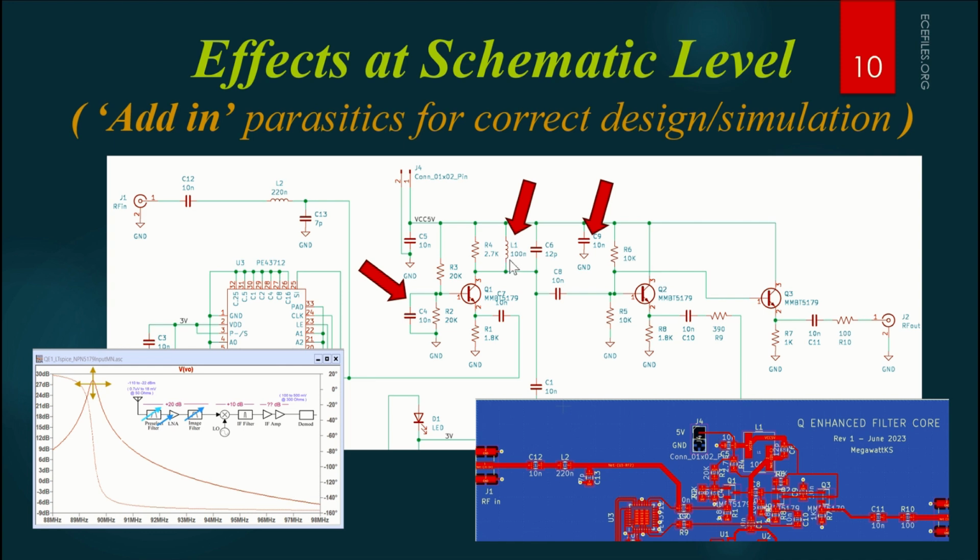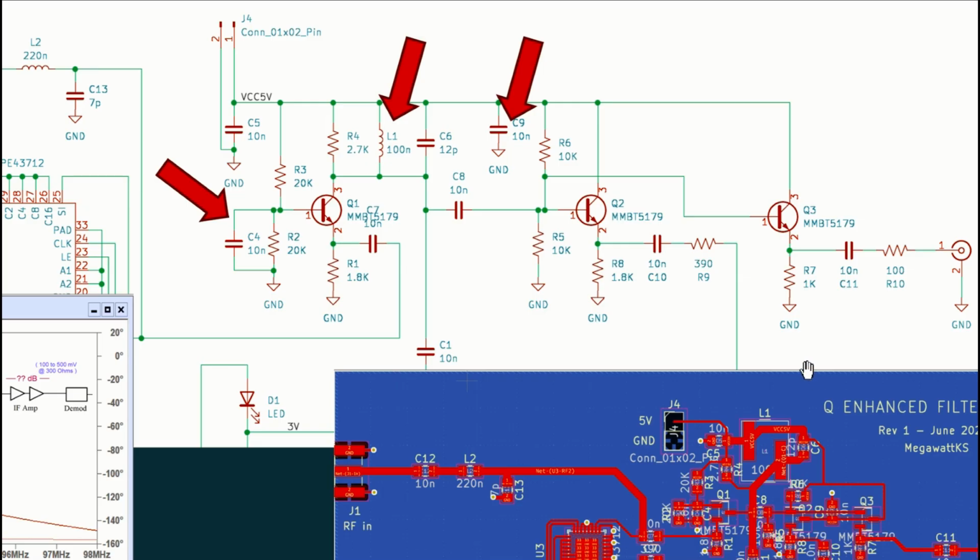And before we leave this slide, let's note that I've got an arrow pointing to the inductor. Why is that? Well, that inductor is here in the layout, and it's 100 nanohenries, but that's what the manufacturer measured from this terminal to this terminal. But there is, in fact, an extra trace length here. There's the length of C6, and then when it comes back to this terminal. So that's in series with the 100 nanohenries. So maybe it's 110 nanohenries, but that might matter a little bit. So you need to think about these things.